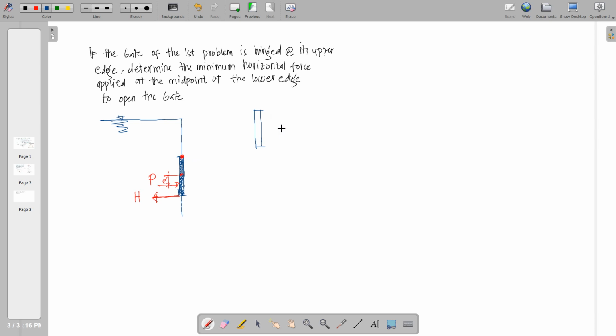Again, considering the free body diagram, we have the value of P equivalent to 98.1 kilonewton, and then the required horizontal force here, say just the same. From the centroid, there will be a concentration of the weight equivalent to 0.8 kilonewton.